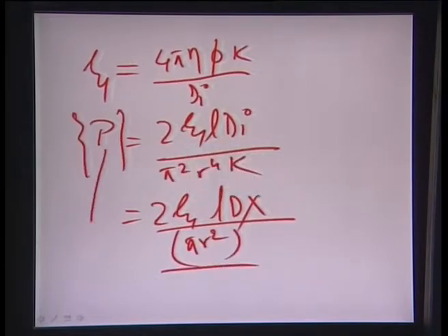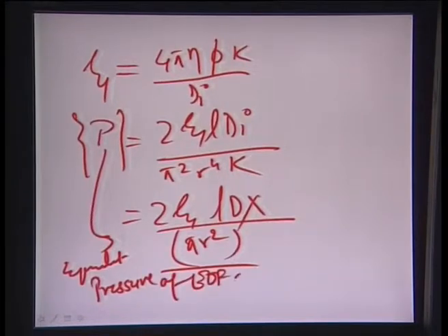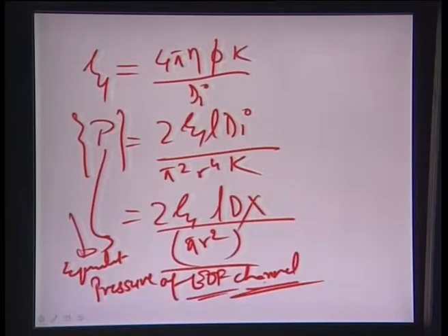This is essentially the equivalent pressure of an EOF channel. So, you can consider the amount of pressure head that is imparted onto the fluid by virtue of the EOF, or the electroosmotic flow, is essentially this P.